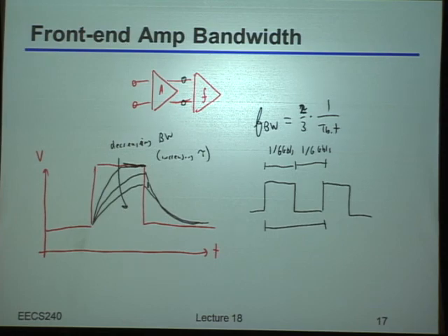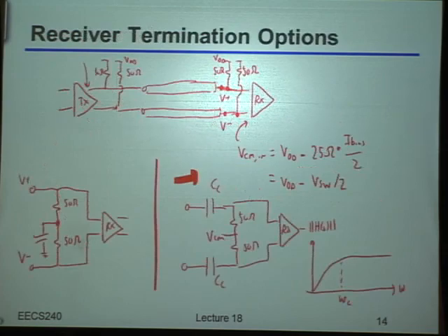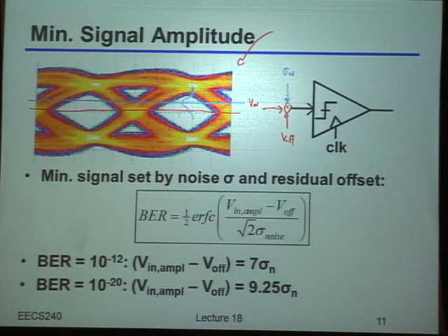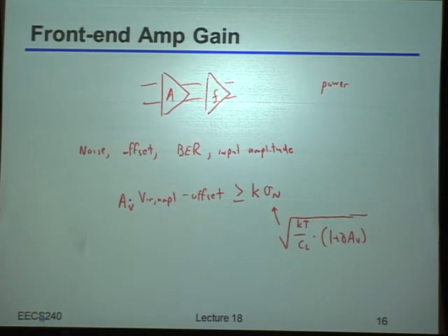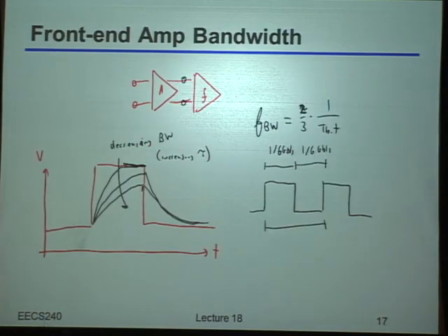Well, when you say the middle, it's typically, let's say, in the middle of the quote-unquote eye diagram. But if you think about, let's say, this picture right here, it's actually right at that peak point, right? Which if you lined it up, if you took out the channel delay, that would actually be at the very edge of that transmitted bit, because that would give you the most time to actually settle the amplifier. So I guess, depending on whether you like thinking about eye diagrams or voltage waveforms, in the eye diagram, it's usually in the middle.